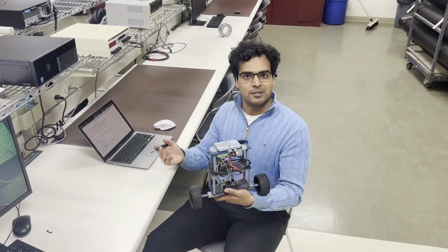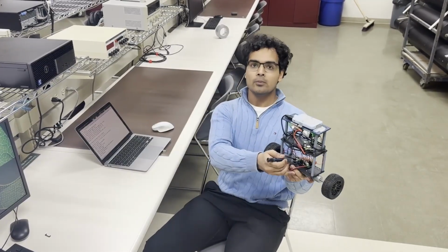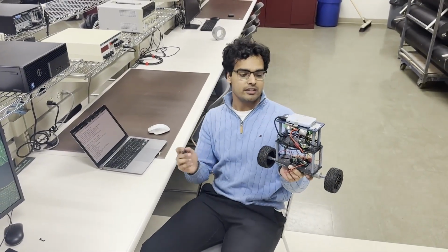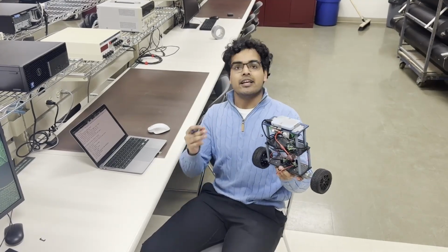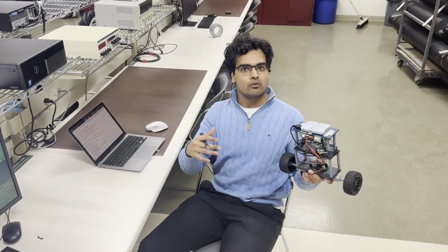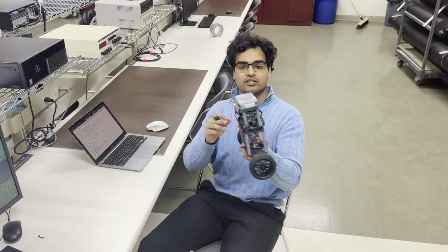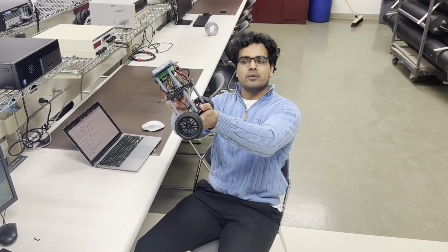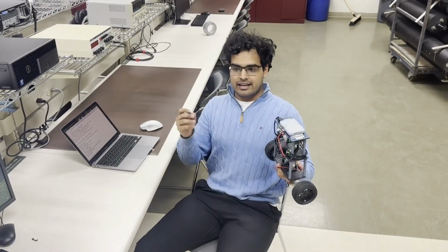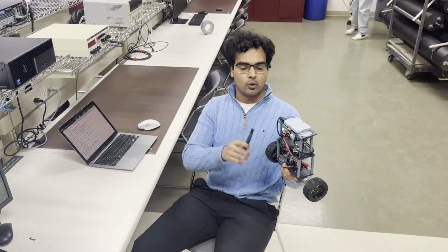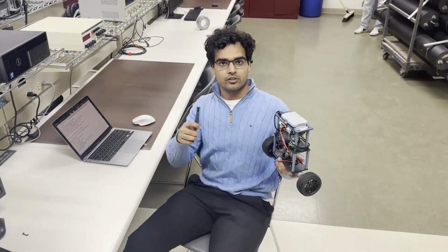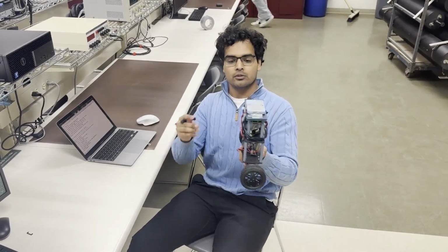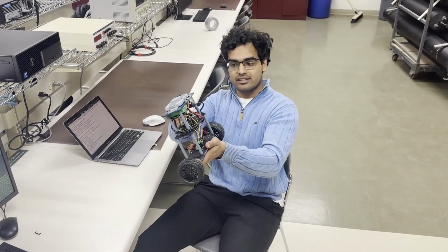So how does our robot balance itself? Well, it uses an onboard IMU to determine the current angle of the robot. It uses a gyroscope and an accelerometer blended together to give us the current angle of the robot, whereas this would be 0 degrees and this would be about 15 degrees. Now, the PID uses proportional, integral, and derivative terms. The proportional term corrects for current errors in the system.